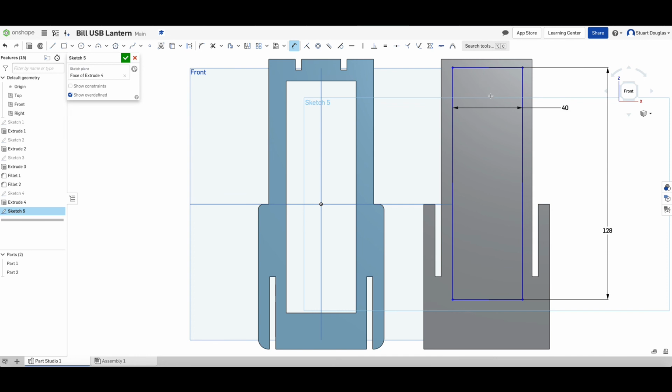However, as you can see, the rectangle has moved closer to the top this time. So what we need to do is again make sure that it's aligned properly. To do that, we'll pick the bottom of the rectangle here, pick the bottom line, and last time we made that 20, so again we make that 20. That shifts the rectangle into the correct place.